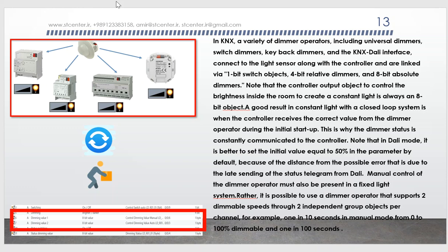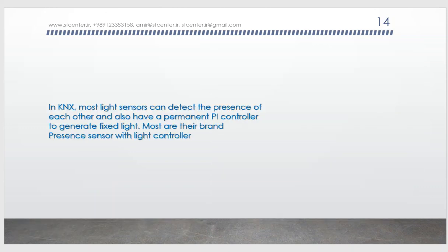We can have other types of actuators that are installed behind the keypad or in a ceiling instead of the electrical cabinet, and so on. So the important thing is that you should always go to the manual, check the group object, and make sure it provides what is required. But nowadays most of them, 99%, provide what you need.